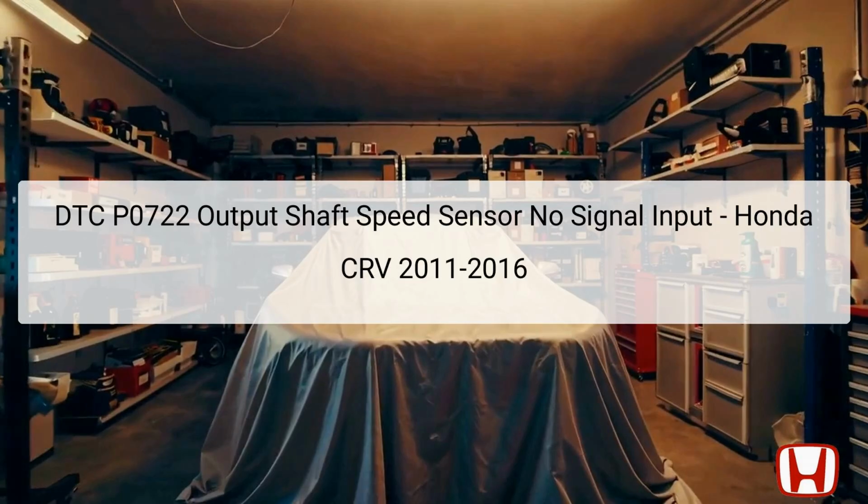Before proceeding, it's important to record all freeze frame data and onboard snapshots using the Honda Diagnostic System, HDS, as this offers insight into vehicle conditions at the time the DTC was triggered.